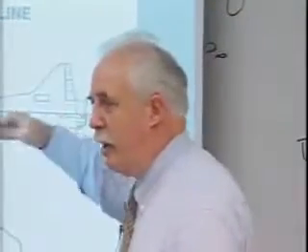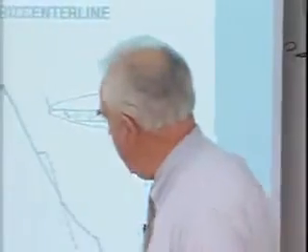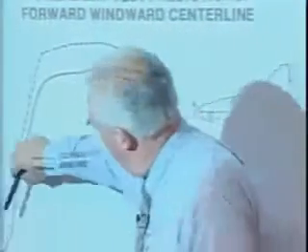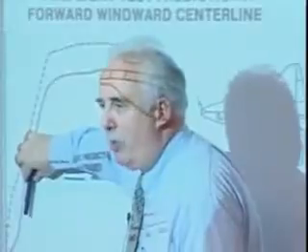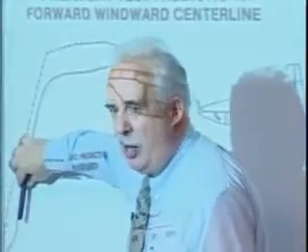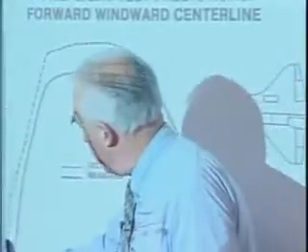Now, what we did is we computed at different times through the trajectory, and then there were correlations to get the history. The prediction, this is JSC prediction, is right here. Now, we didn't worry about exceeding Stanton number 1. That is, we didn't worry about the heat transfer being higher than the energy flux to the vehicle up here, because if you look at these numbers, we should have accounted for that, but it's not that important.